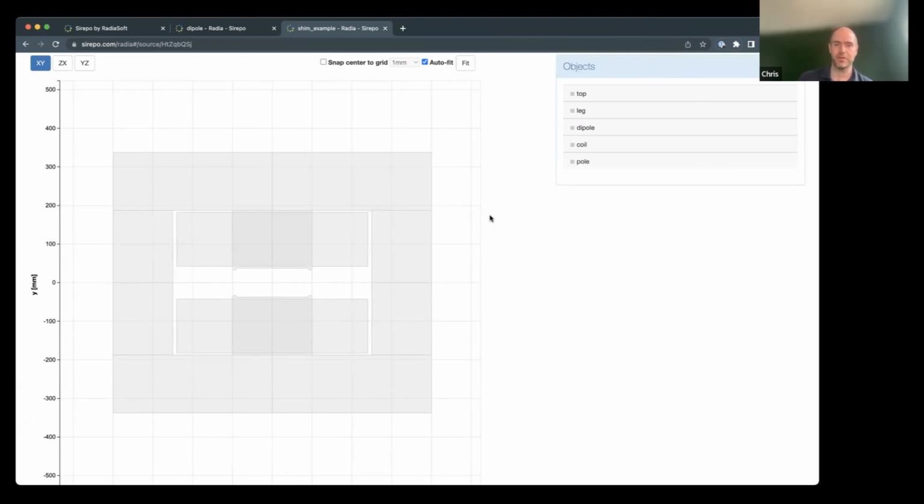And that is going to be reflected when you actually take measurements of the field, even in the gap here. Depending upon the entire setup, it can be pretty sensitive to how you do that segmentation. So yeah, it does pay off to play with the segmentation some and make sure that you're fully converged and getting consistent results as you change the segmentation before trusting the simulation completely.